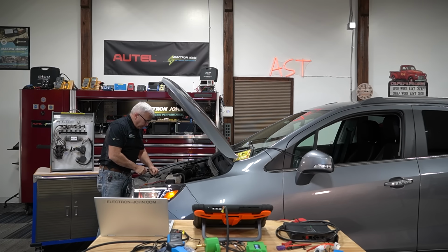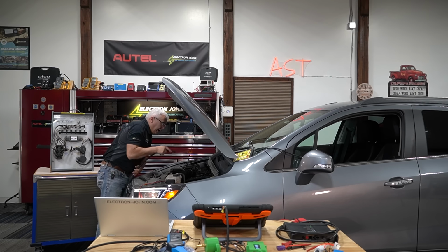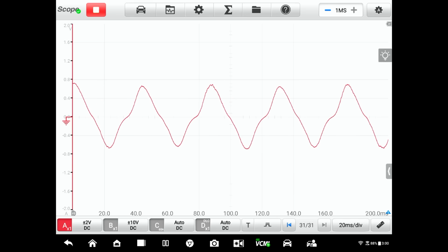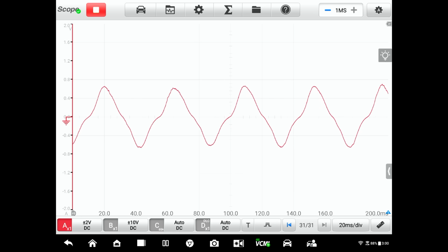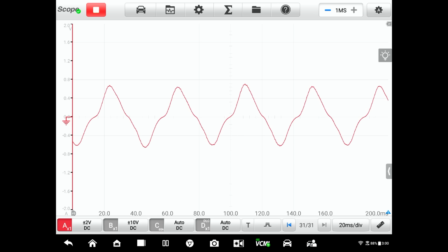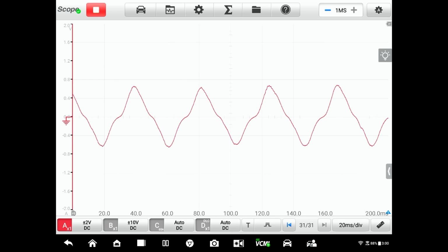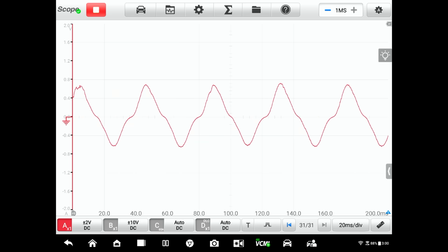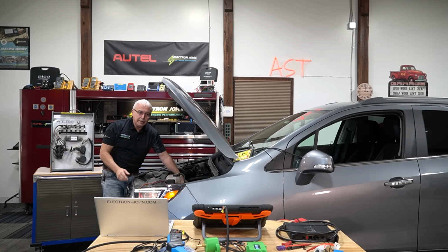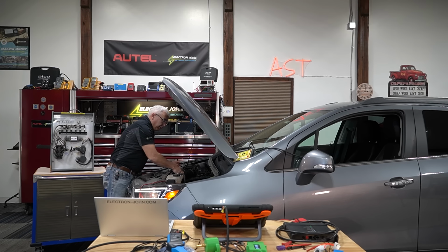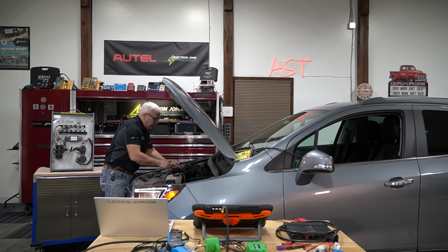Not sure if you picked that up on the audio or not, but because it's mass airflow, once I pulled that dipstick tube out, the engine started to run a little bit rough. And here I'm displaying a crankcase pressure transducer waveform. And again, I'd be looking for something that was not uniform. And I'd take the same series of steps, so if something was out of whack here, I wouldn't necessarily know which cylinder was what, so I'd have to turn on channel 2 and get some type of pressure or some type of RPM input here for the firing order